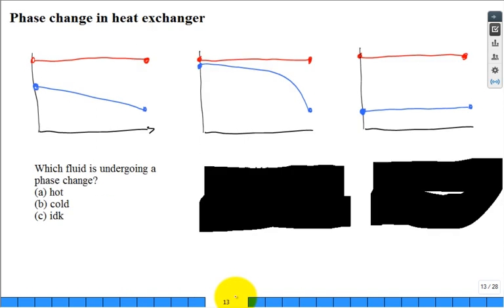The whole idea is we have this heat capacity rate. And when we want a large heat capacity rate, we talked about really turning on the pumps and pushing a lot of mass flow through it. But you know what? How can you get a huge heat capacity rate near infinity? Think about having an effective specific heat near infinity. Essentially, condensing or boiling, changing phase, gives you a huge heat capacity rate.